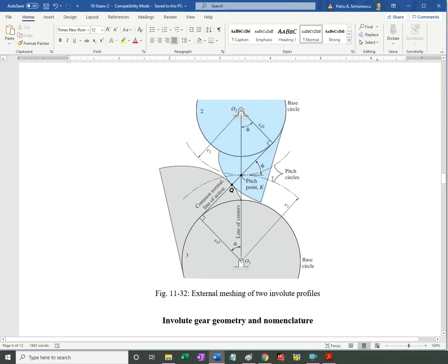And these are standardized, and again, they are for gears with zero backlash and with no addendum modification. Remember that X value that was changed, we made it negative 0.25 and positive 0.25. So when that's zero and I have zero backlash, the ensuing pressure angle between the two gears is going to be the same as the slope angle of the generating rack.